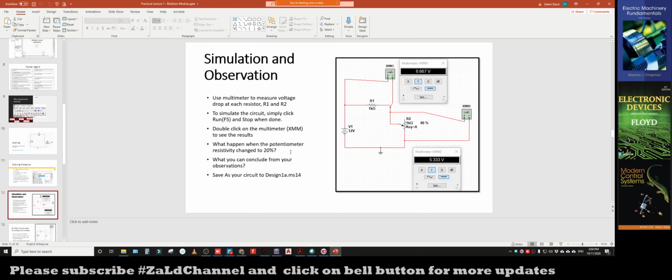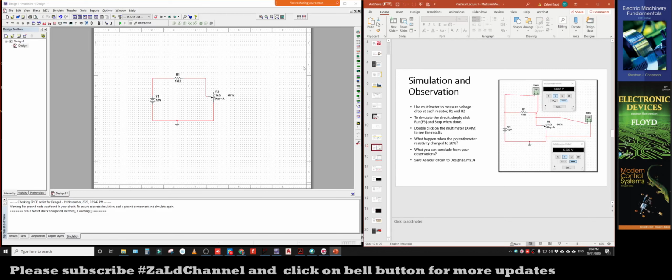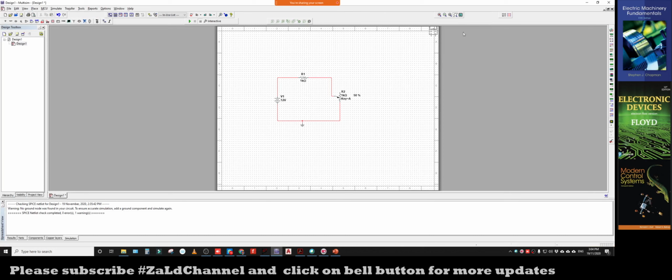And then once we finish constructing this circuit, what I am going to do now is connect the multimeter. Since this is the voltage divider circuit, I want to use the multimeter to measure the output across R1 and also the output across R2. So I'm going to use two multimeters. Just select the multimeter here. This is the multimeter that we are going to use to measure the voltage across R1. So take the positive probe of that multimeter, connect it to one terminal of the resistor, and connect the other probe to the other terminal of the resistor.